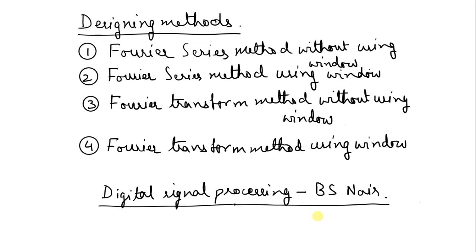So good evening. Today we will start with the designing methods for the FIR filters. Okay. So there are four methods: Fourier series method without using window, Fourier series method using window, then Fourier transform method without using window, and lastly Fourier transform method using window.